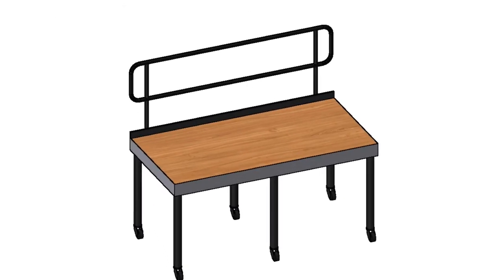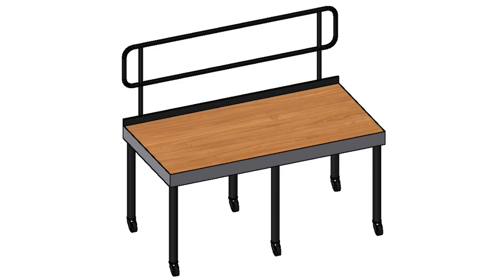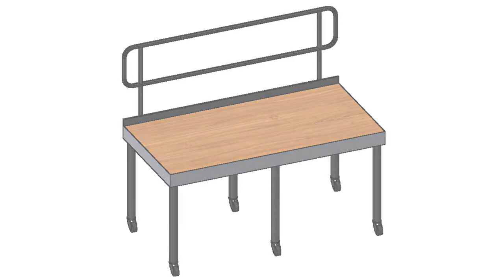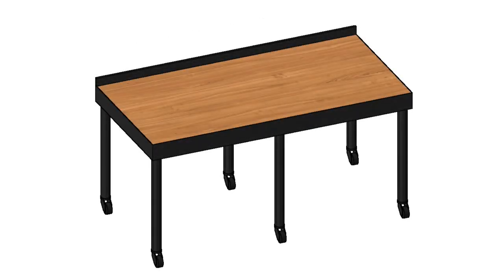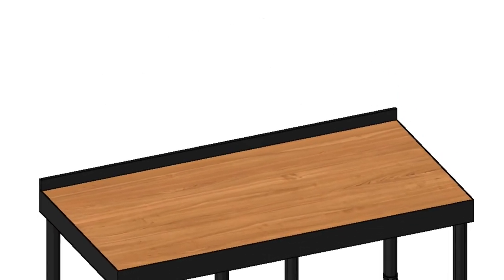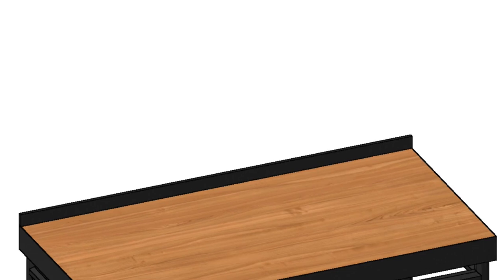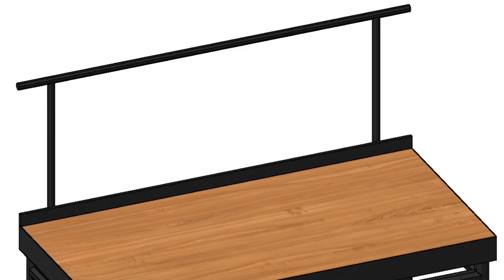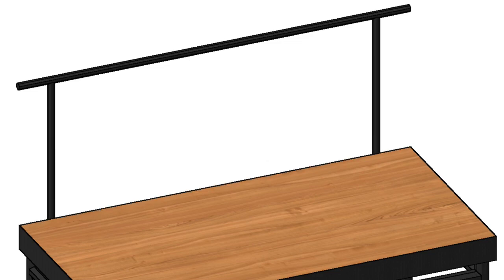Legs Basic will give you the simple straight legs that can be customized in shape and color below, in the Leg Structure Details section of the Object Info palette. Deck Details allow you to change the attributes of the top or the deck itself. Rail Details is where you can add a railing and or a toe to the various edges of your deck.